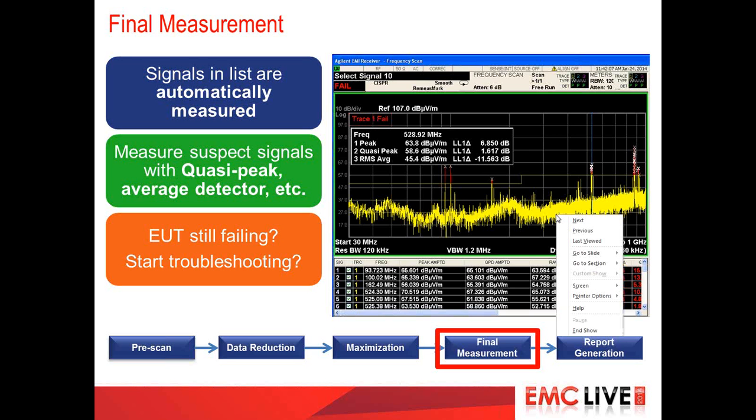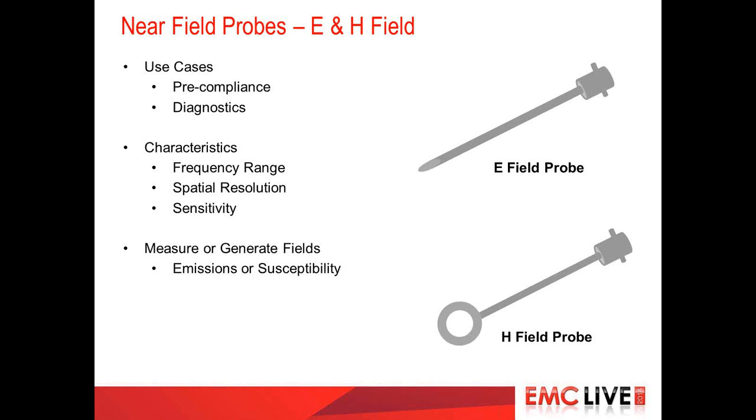And then lastly, we've just talked about using probes for measurements, but you can also use them to generate a local field. Imagine you're wanting to test your processor or your little IC, hook up a signal generator, generate a local field, see how your device under test reacts, and you're able to test different components that way. Now for antennas, I don't have time to talk about each one of these, but some typical antennas used for EMC measurements.